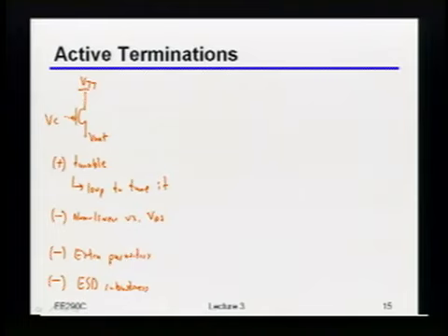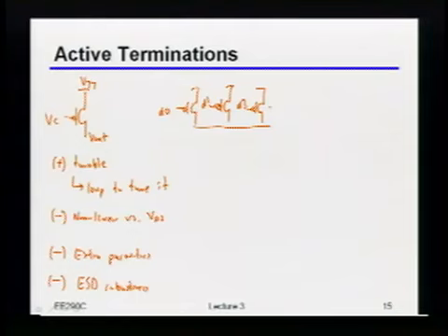I'll give you a hint. This is like the analog way of doing things. What's the other way of doing things? Digitally trimmed resistor? Yeah, just a digitally trimmed resistor, right? So, of course, that also is just something quite straightforward. You just take a bunch of these PMOSs, you segment it into different little legs here, and maybe I'll make it smaller so I leave myself room for the last version. Right, you have some digital codes on here, D2, and of course this just continues depending upon how many different legs you want. And basically you can, of course, do the digitally controlled version of this same thing.